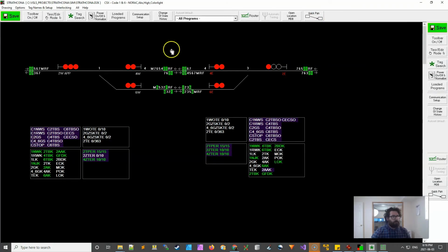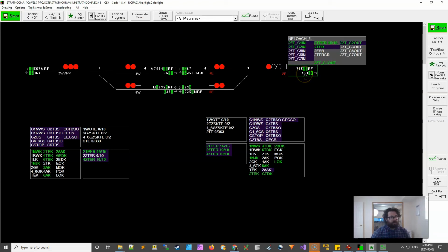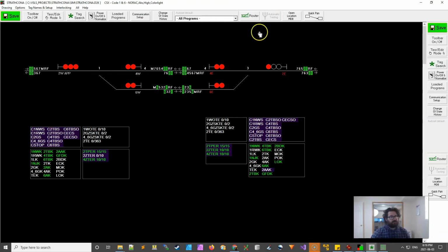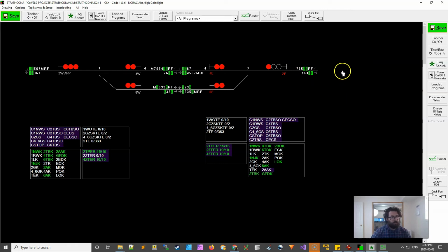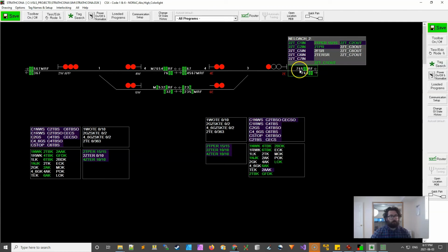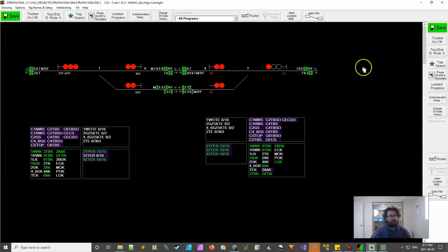So here we've got a track plan. Everything here is already set up, and these symbols here represent coded tracks. So you can see in this particular location, we have 1, 2, 3, 4, 5, 6 pieces of coded track. These ones out at the end are like what I was talking about earlier, where they're basically a boundary condition for this simulation. So the user is able to set up the values of the input on the coded track here as desired for testing, rather than thinking about having to set up conditions on an interlocking in order to generate those codes.